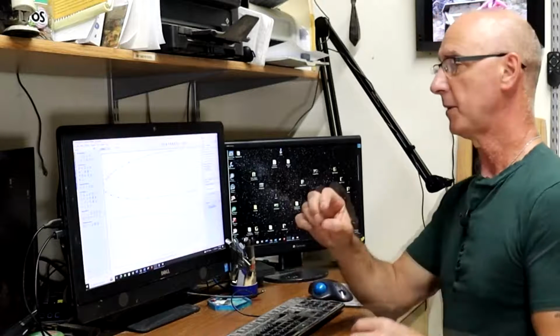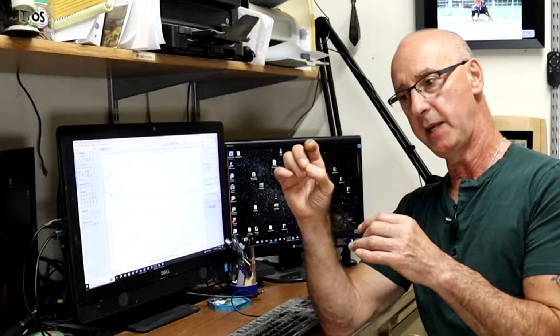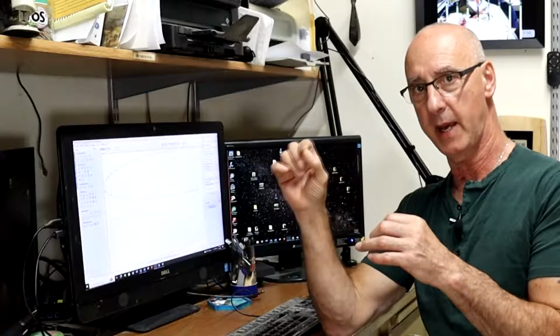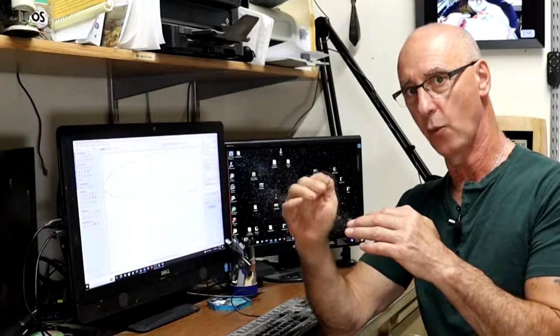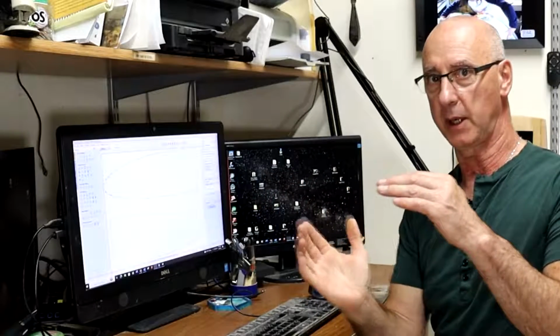So what I have found with individual components, with a bunch of stuff to cut out of the leather, it's easier for me to work on that one component at a time, work on getting the starting point right, getting this initiated so the drag knife is on the waste side of the work. It's easier to do that when I select one, tool path one, select another one, tool path another.